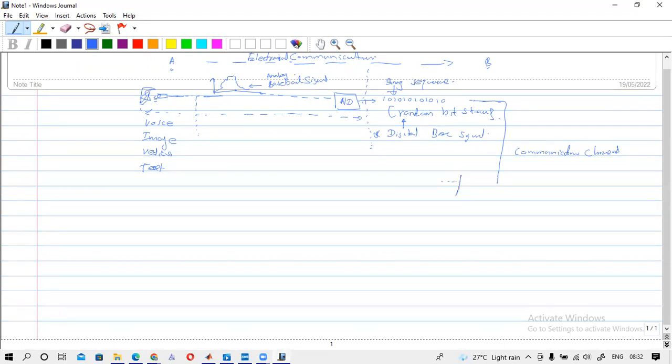That process we call line coding. There are many line coding methods. I think the basic ones are NRZ unipolar, NRZ bipolar, RZ unipolar, RZ bipolar, and Manchester. Anyway, we have to use a line coding technique to convert this bit stream to an electrical signal.